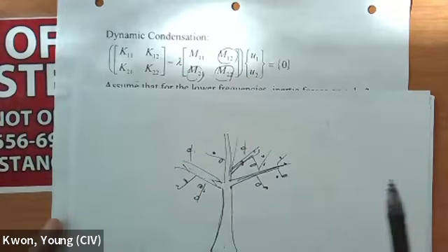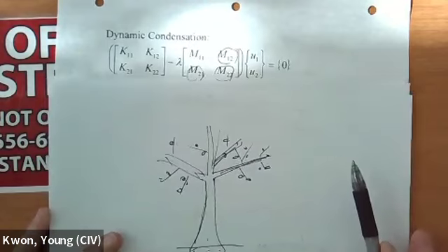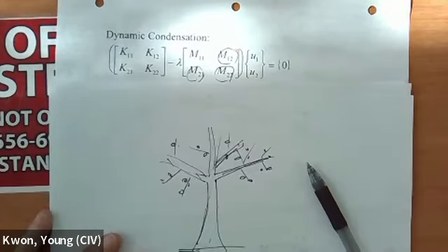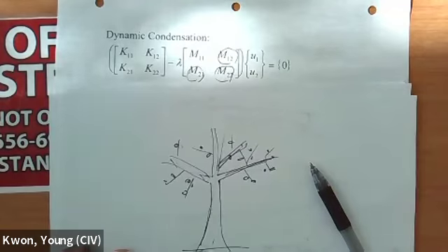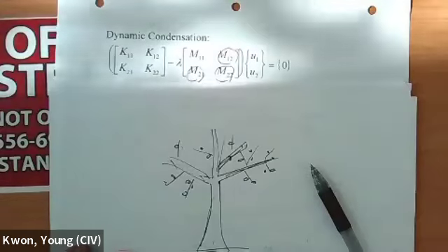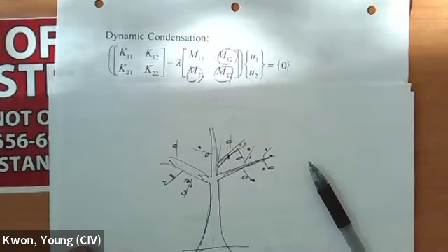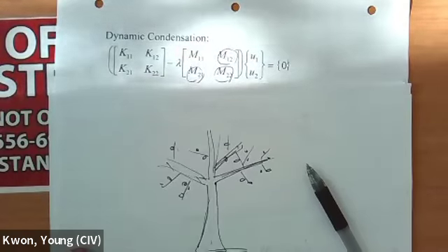However, sometimes it is not clear whether I can condense out some degrees of freedom or not, then you had better not do that. Just leave it alone and do the full calculation, even if it takes some extra time. But if you're sure, and you really want to save computation time, then you can do that.